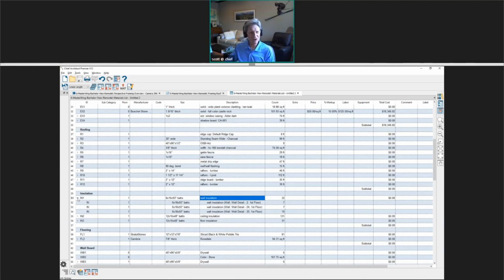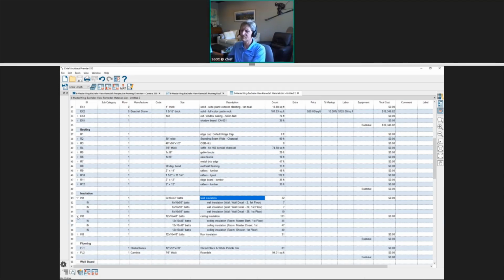Yeah, so that's a good question. Chris, are you out there? Could weigh in if there's a way to change the insulation from bats to rolls. Yeah, I'm here. There are ways to accomplish that. The best way to do it is to work it out based on some kind of a formula. You can type in a size and change your size from saying bats to, you can just call it a 6x16 roll, or just 6x16, and then you can set it up to calculate linear feet. And you would just do that by using a formula.